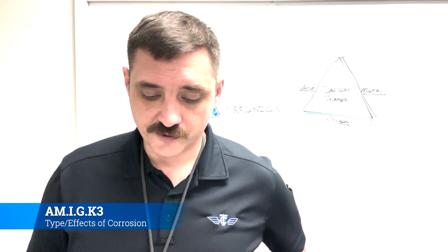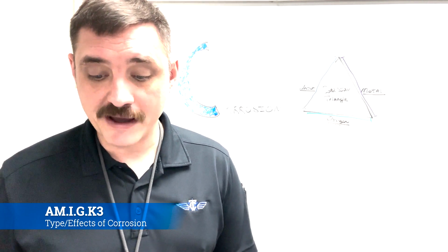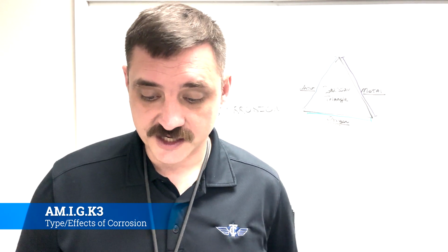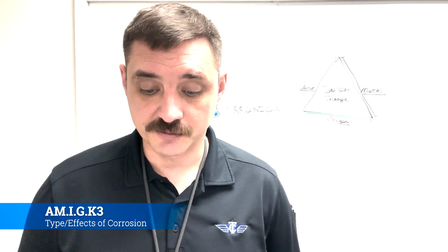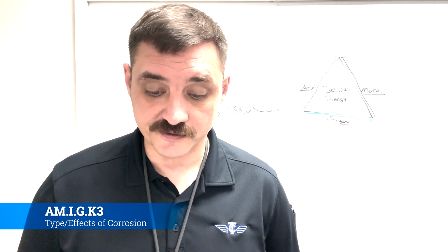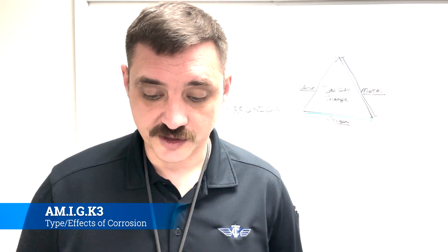Okay, fretting corrosion. That's an interesting one. Fretting corrosion is a particularly damaging form of corrosive attack that occurs between two mating surfaces, normally at rest with respect to one another, and subject to slight relative motion. It's characterized by pitting of the surfaces and the generation of considerable quantities of finely divided debris. Since the restrictive movements of the two surfaces prevent debris from escaping very easily, extremely localized abrasion occurs.